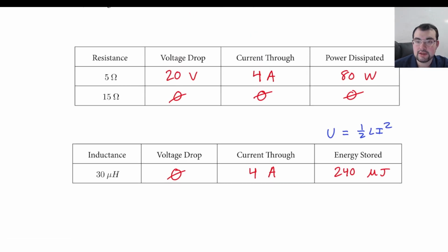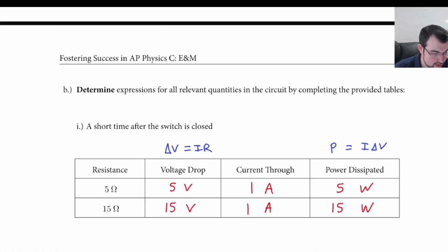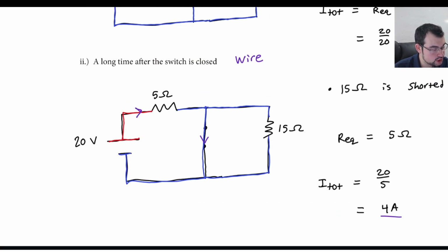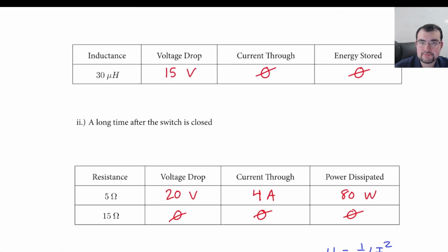All right, so we see that the inductor doesn't fully store energy until the steady state. It doesn't oppose current, it opposes changes in current. And there's no change after a while, so it's fine.